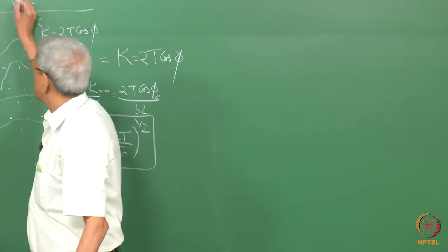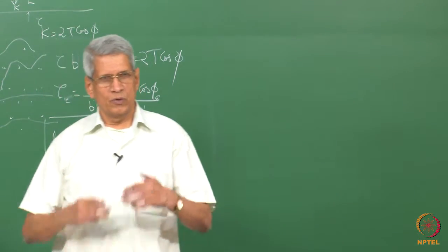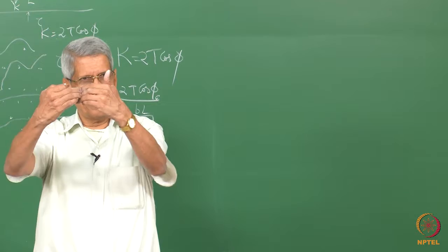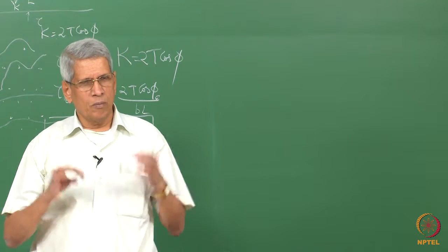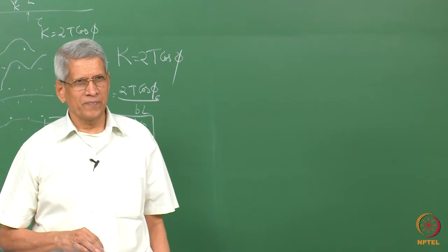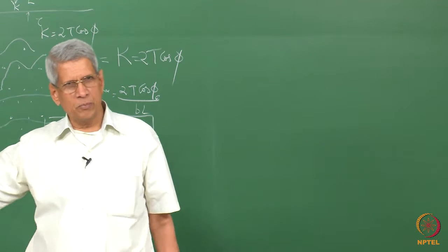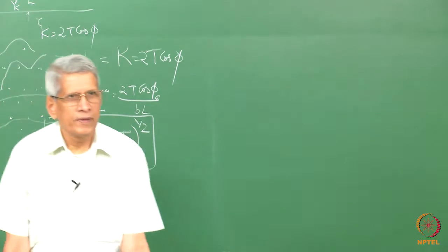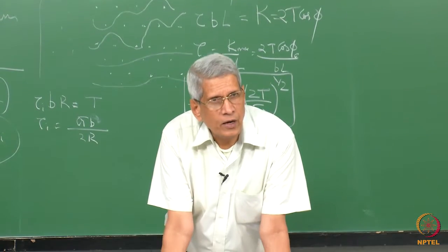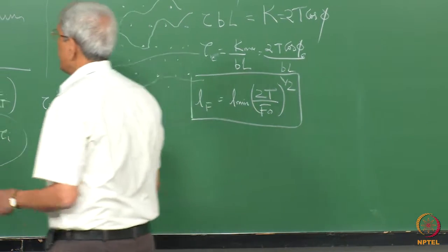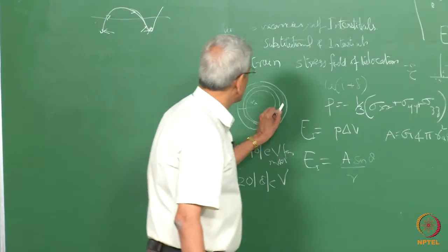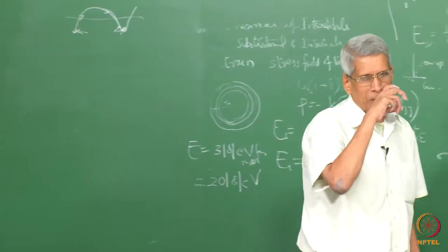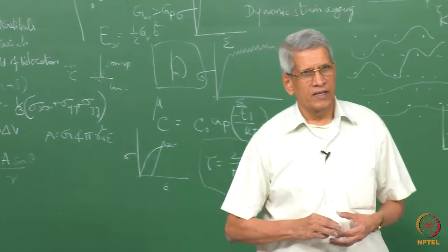The modulus will determine what is the stress which is required. Suppose this has a modulus which is higher. So to account for the modulus, if it bends a little bit, the line tension becomes sufficient. It can make the particle cut through it. So modulus also plays a role to decide, correct? Another is that suppose there is a lattice parameter misfit. We have seen that interaction which can happen. Not only that, in that particular case, there is going to be a strain which is accommodated around it. This strain we call a coherency strain, which we talked about in the last class.